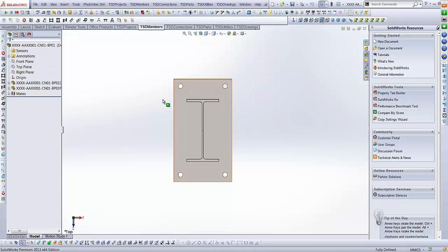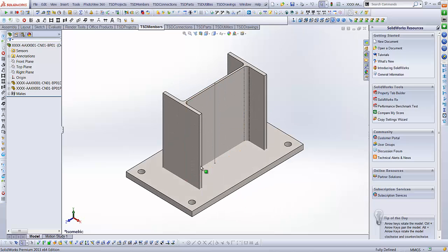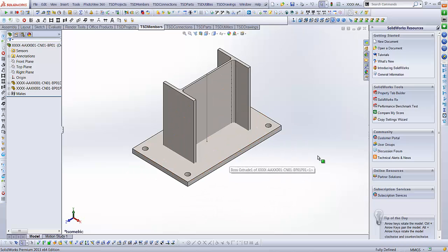I've just double clicked on the plate to get the plate to change. So it means that if I change this Weldment member, that plate is going to change to suit it. What you'll also notice, the plate itself is sitting down inside, the dummy member is sitting down inside the plate. What I'm going to do is trim it.